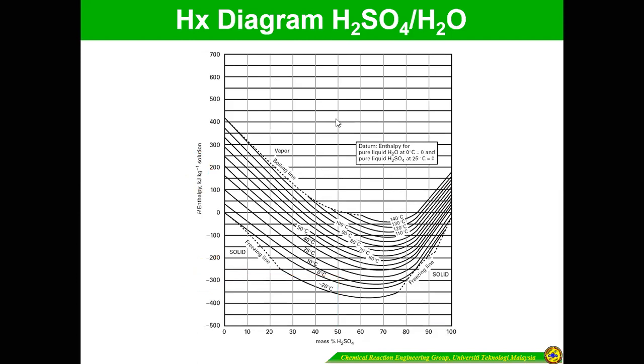Yes, this graph is only for H2SO4. If it is HCl, there is a different graph. There's going to be a different graph. So you can refer to any engineering book, or we can calculate from the heat of solution, or the heat of formation of the solution. That is also possible. If not, we cannot determine it from the graph. Later I will show you how to calculate. Generally the example is only for lithium chloride, but for the other components, solute in solution, I will show you which data you can refer to.